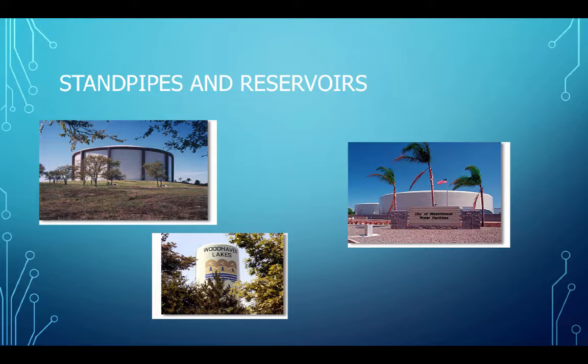Here's some other surface reservoirs. Reservoir, reservoir, and this is a standpipe. The difference between the surface reservoir and standpipe is in a surface reservoir the diameter is bigger than the height. Standpipe, the height is bigger than the diameter.